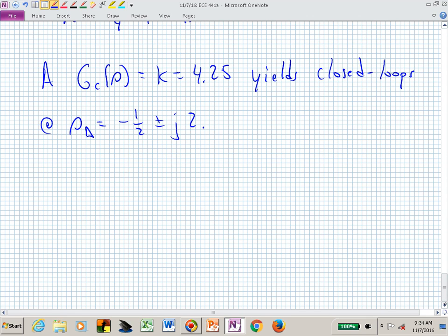And as we just earlier had determined, our settling time is not really what we wanted. Our 2% settling time is 4 time constants, which is 4 over sigma. That's 4 over 1/2, which is now the 8 seconds.